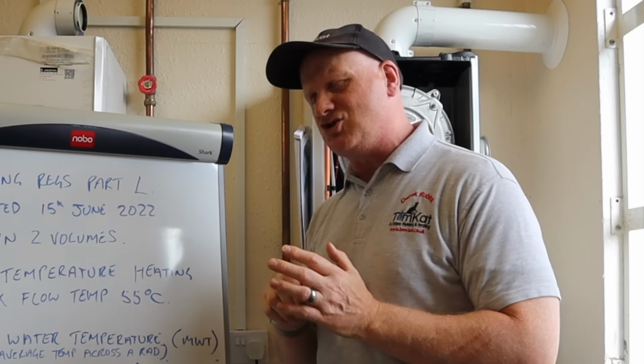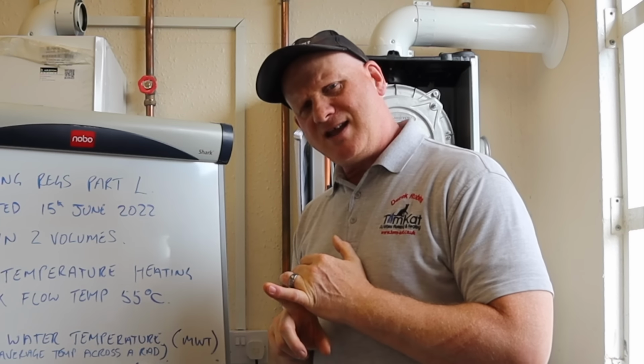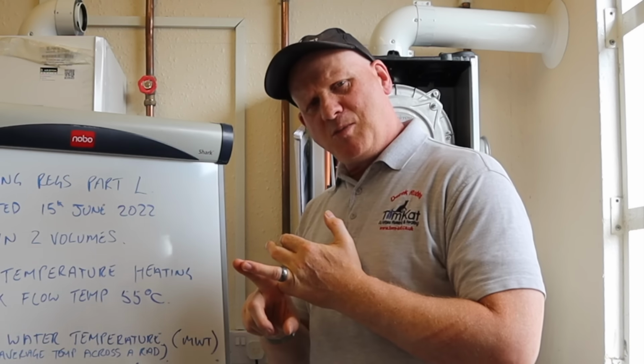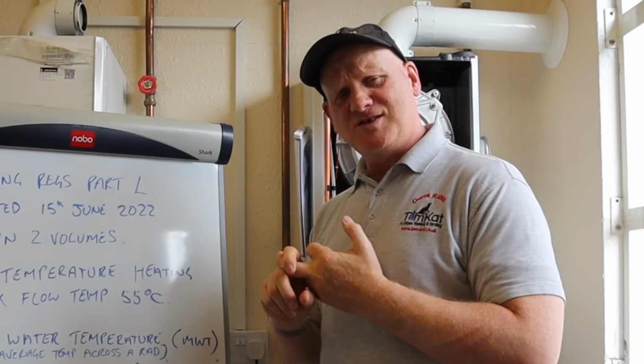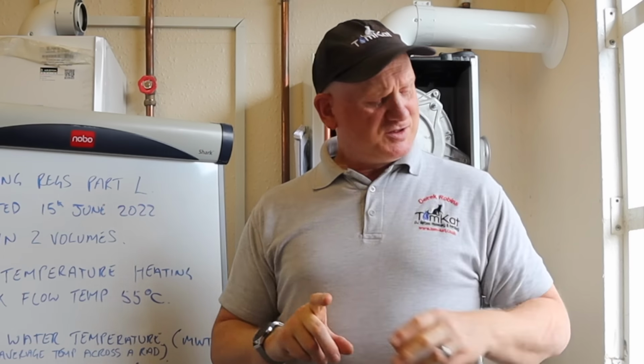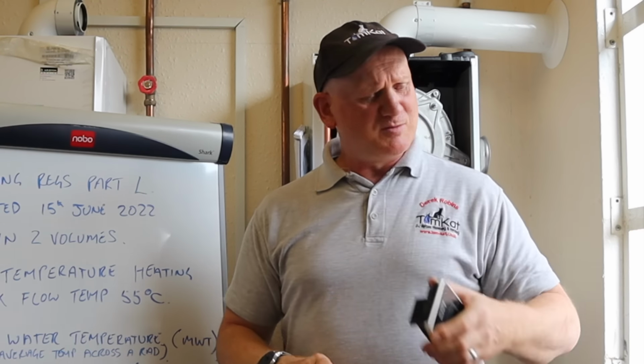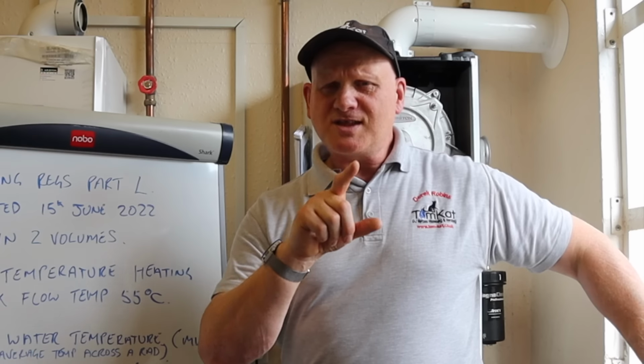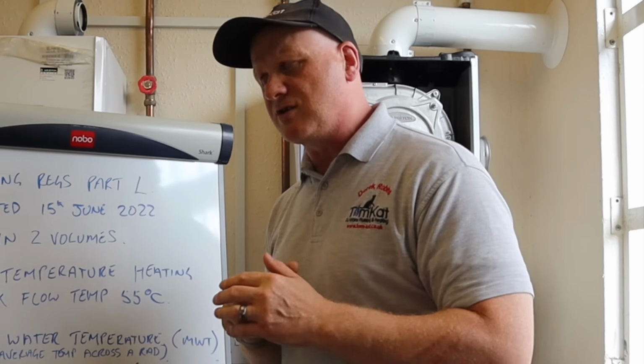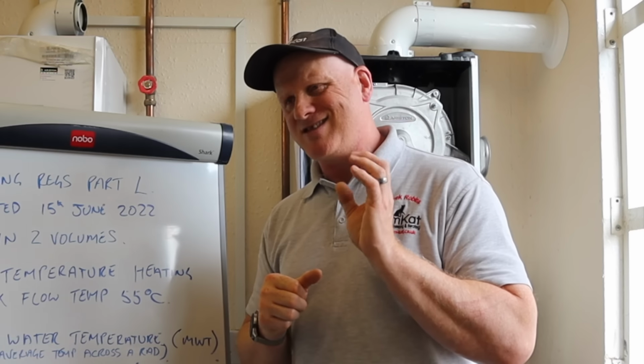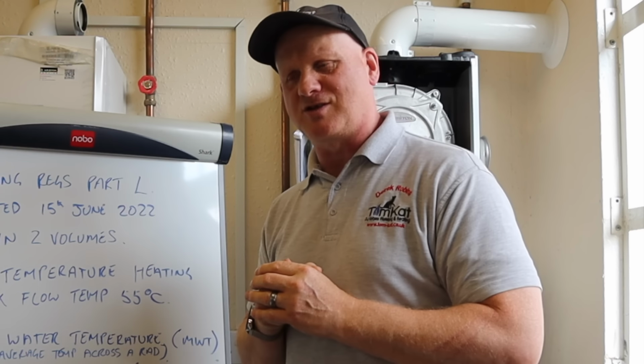So it's not just adjusting your flow temperatures. The considerations are: are your radiators big enough? Is your pump big enough? What type of system do you actually have? Do you have a room thermostat? Have you got thermostatic radiator valves? And what temperature do we set these thermostatic radiator valves to?